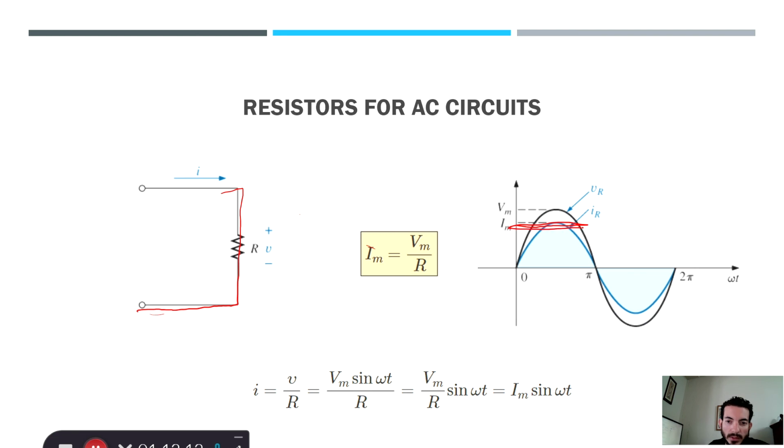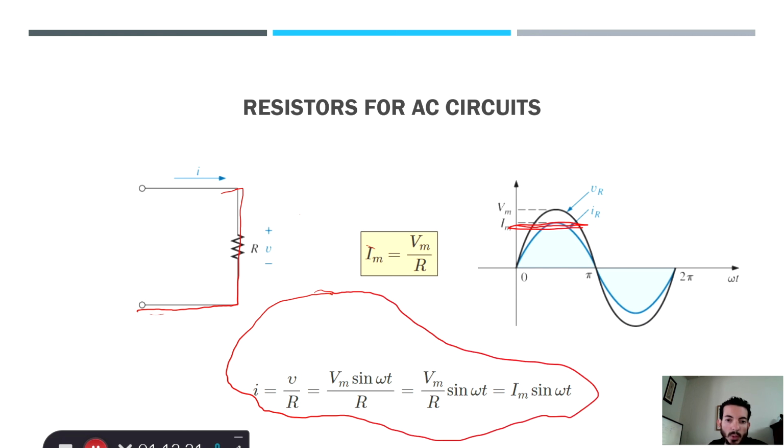If you had certain power after going through a wire or some type of resistance or the air, the amplitude is less, but the phase is exactly the same. So this is very important when we start talking about impedance and reactance and all those things. Sine waves going through resistors have the same phase but different amplitudes, usually reduced.